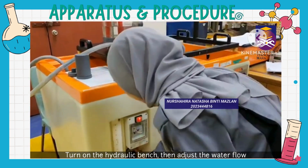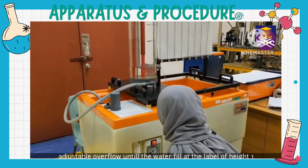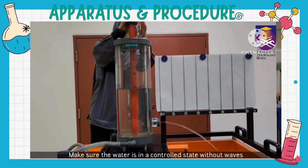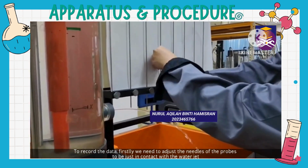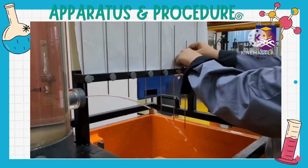Turn on the hydraulic bench, then adjust the water flow. Pull the overflow until the water fills to the level of height 1. Make sure the water is in a controlled state without waves. To record the data, firstly we need to adjust the needle of the probe to be just in contact with the water jet.